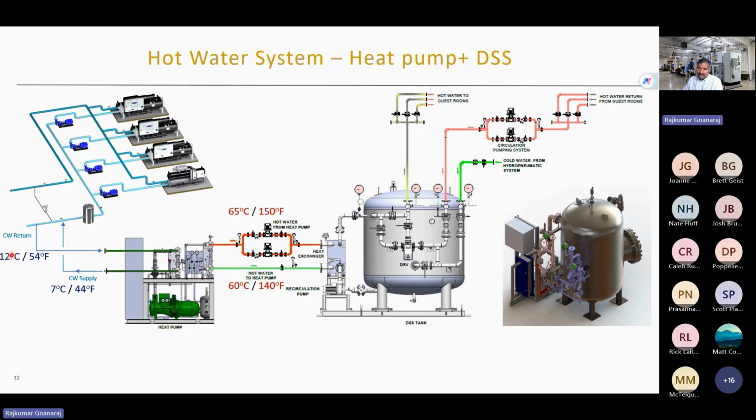They have chillers. From the main chilled return water header, we are taking a tapping of water at 54 degrees Fahrenheit that goes to the heat pump evaporator. The heat pump will cool it down to 44 degrees Fahrenheit and put it back in the same header. On the condenser side, we generate hot water at 150 degrees Fahrenheit that goes to another plate heat exchanger. Because in most institutional facilities where they want to heat domestic water, they will not take this water directly to the heat pump.